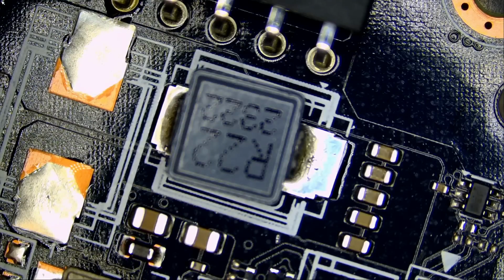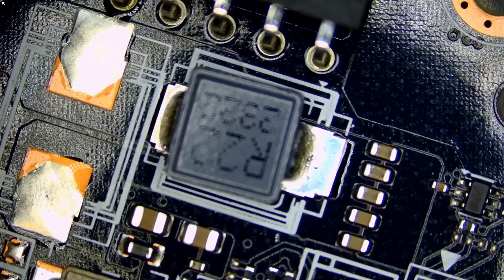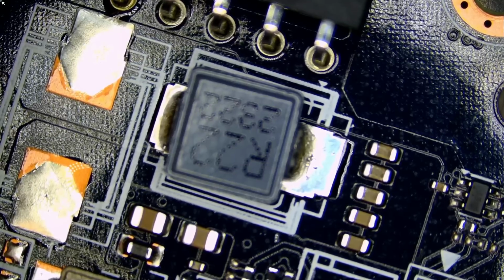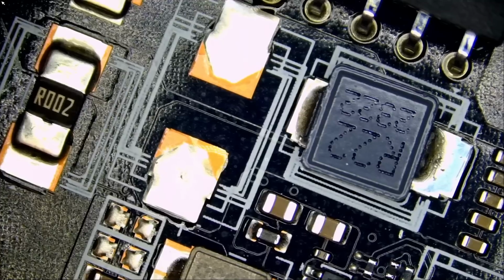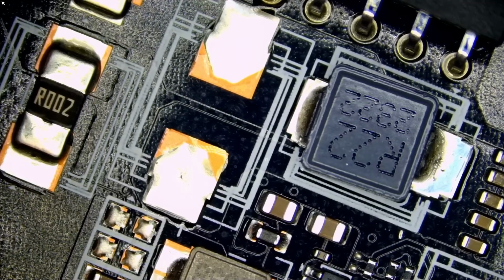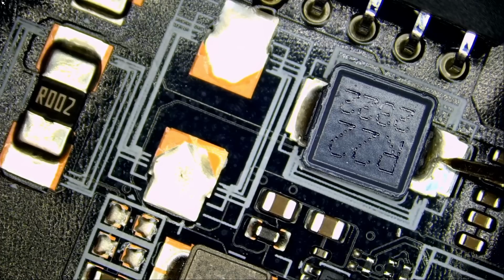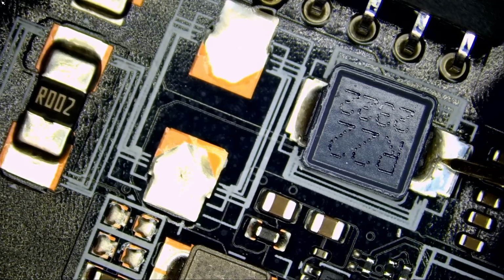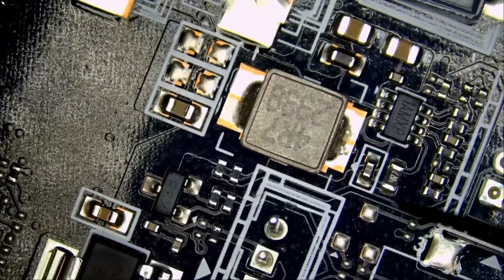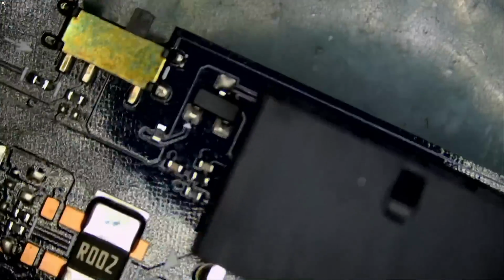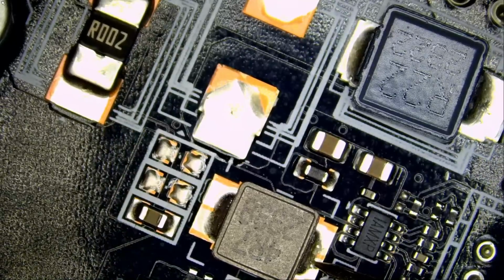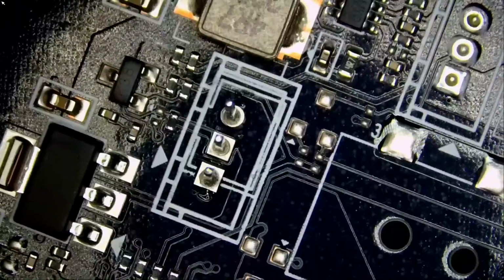Let's take a look at the card. A capacitor, the exact capacitor. I haven't seen a capacitor fail on any video card since I started fixing video cards. Resistance mode, or maybe we can go to diode mode. Let's start by measuring our 12-volt line. 0.472 voltage drop. .569.